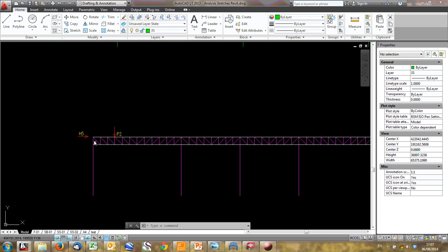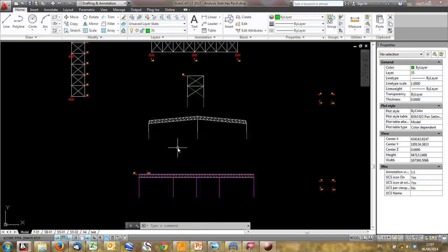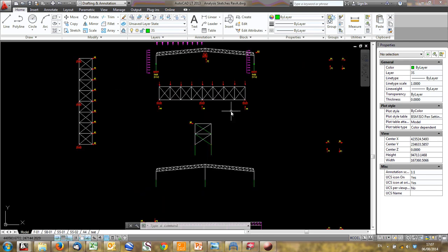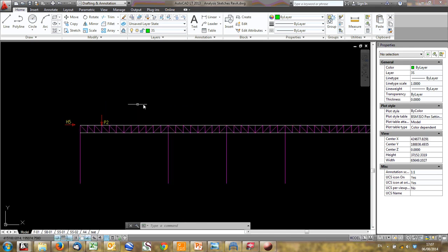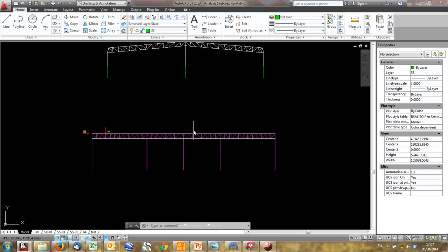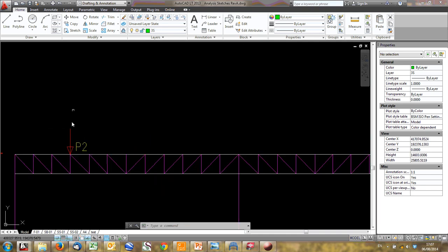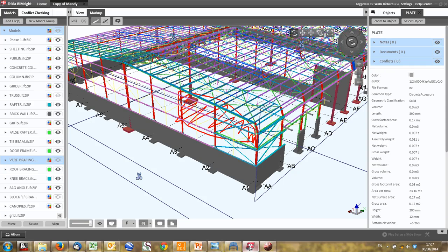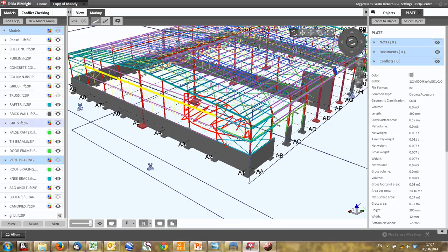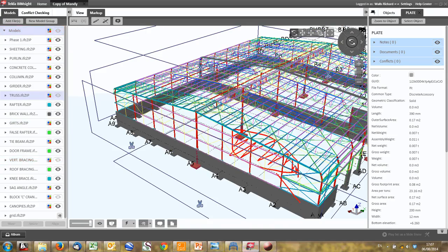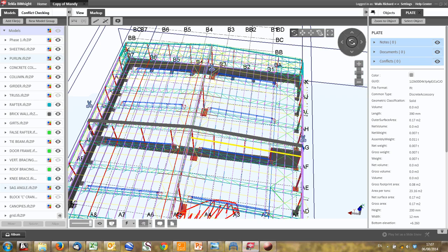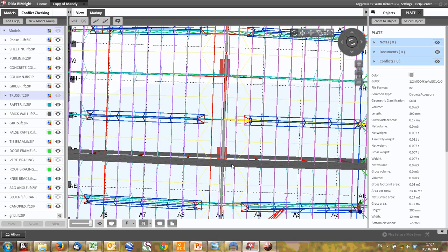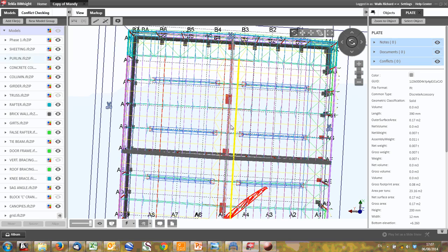The same thing with this girder. You can check if you get reactions from your vertical bracing, or roof bracing, I mean. Does this load match the areas it's carrying? Are these vertical loads basically half the roof? The loads on the girder, if it's a dead or live load, should be roughly half the span from here to here acting on this.